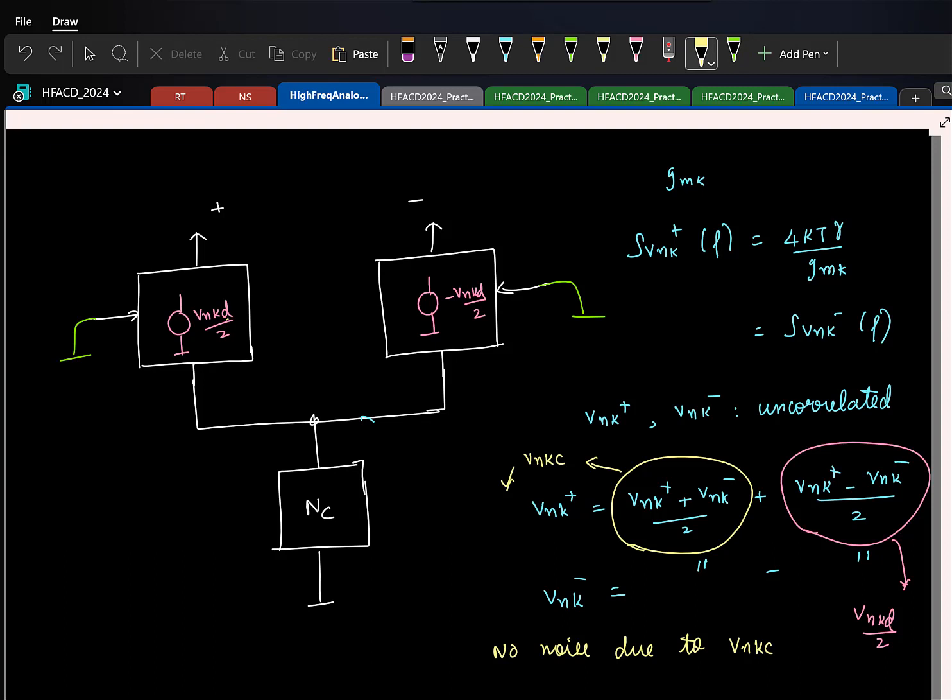It's a differential excitation. Is there something that can be done now? Yeah, once again, all the nodes along the line of symmetry will be 0. So this one is not playing any role. Basically now this is split into two half circuits nicely. Right? The rest of the calculation I'll just hand wave, and then make you work it out in the assignment.